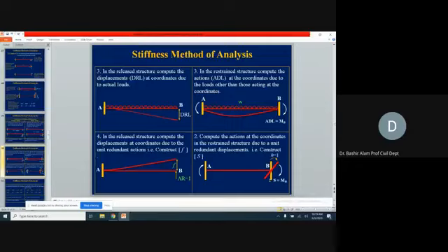Now from the previous slide, we got the AD value corresponding to the displaceable joint. From step number 3, we got the ADL matrix. From here now we got this stiffness coefficient. If we multiply this by the actual displacement instead of D, that becomes stiffness times the actual displacement. That actual displacement is actually our unknown. With the 3 quantities known and this one unknown, we can solve the simultaneous equations, which we are making from the equilibrium.